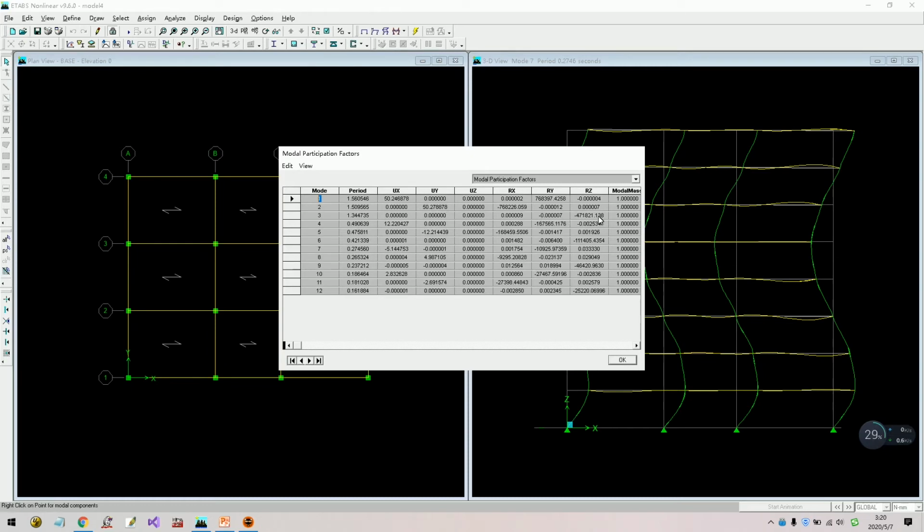It doesn't matter. The one direction movement, and the one direction torsional movement is for the third period, and the second period is a repeat, and the fourth period is movement, and the fifth is movement, and the sixth is torsional. And this is quite common for the regular building, but we need to focus on controlling that torsional will not become the first. This is the most critical option for the seismic analysis.